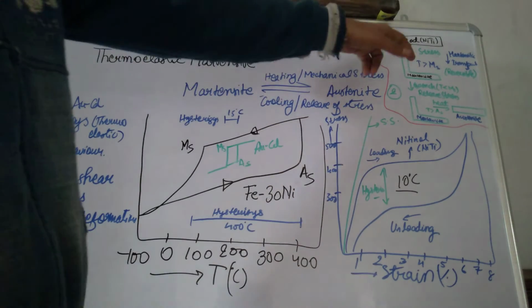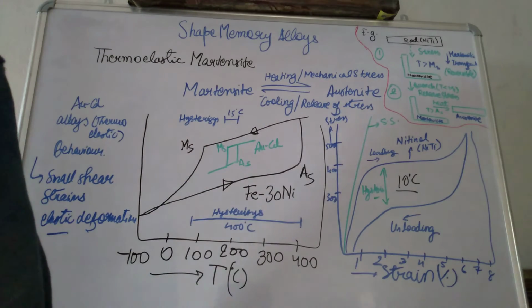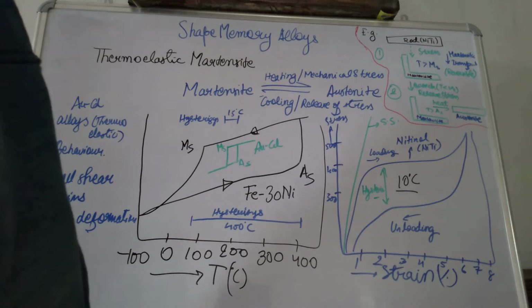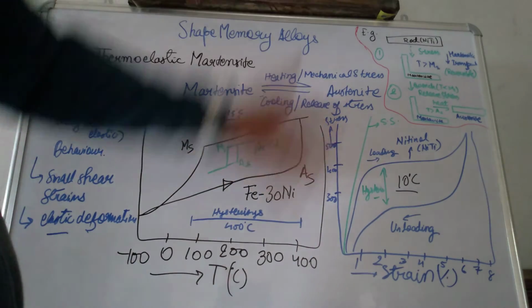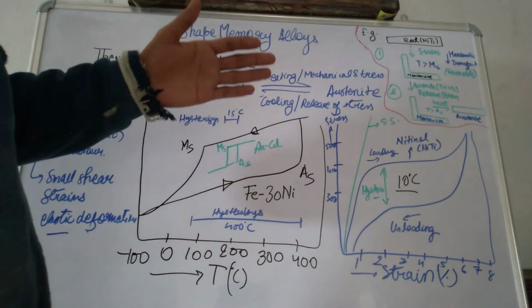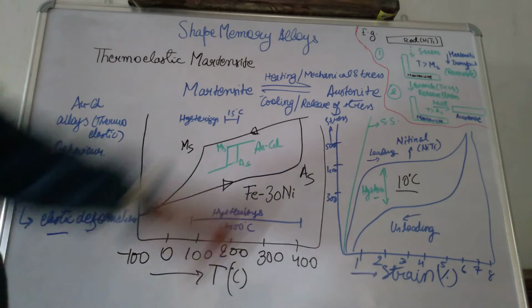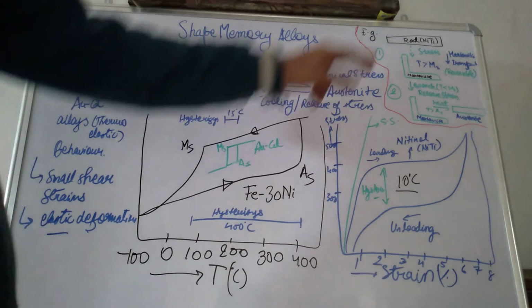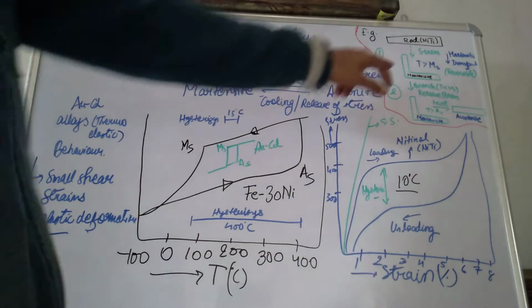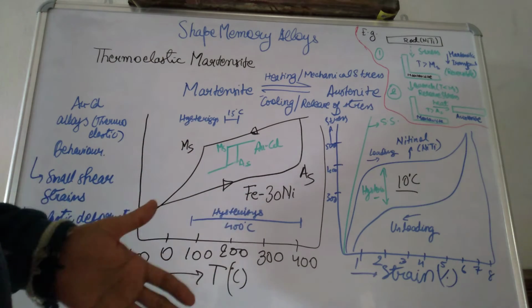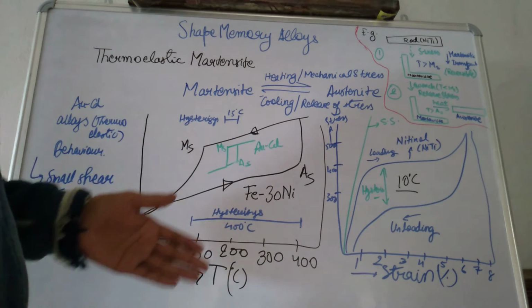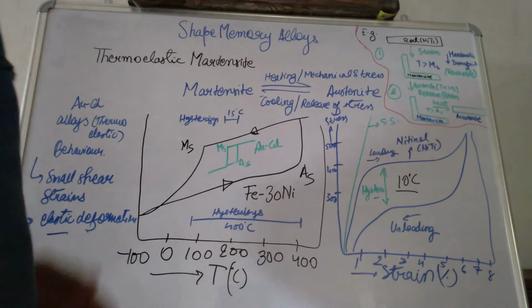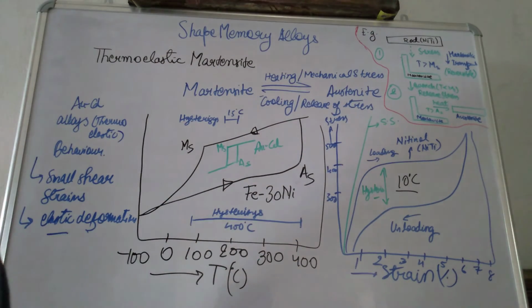If we release the stress, as per the stress strain diagram, it will revert back to the original shape, and the martensite will transform to austenite. Now, if instead of releasing the stress we quench the rod in the L shape below the martensite temperature, then even if we release the stress, the martensite will not transform to austenite, because we have given it thermal activation and it now has a thermal driving force to stay martensite.